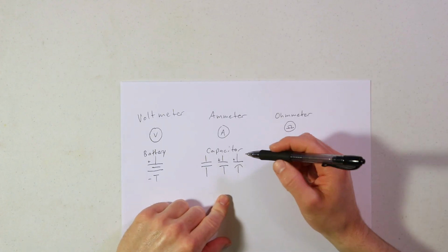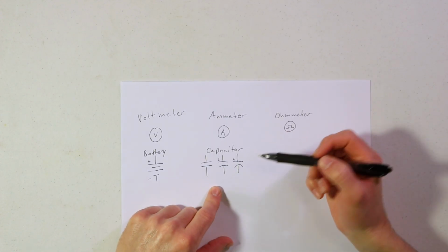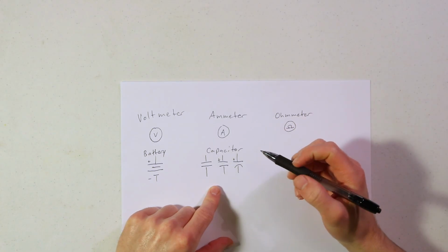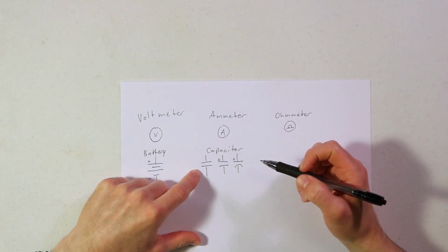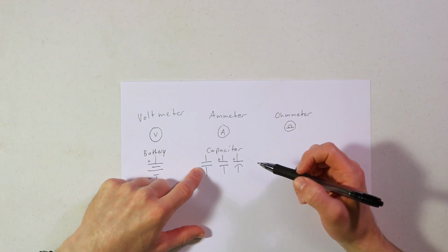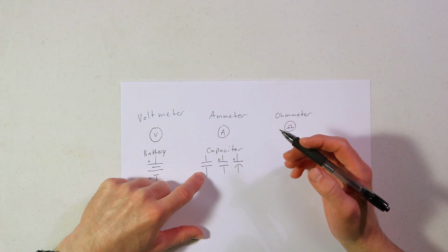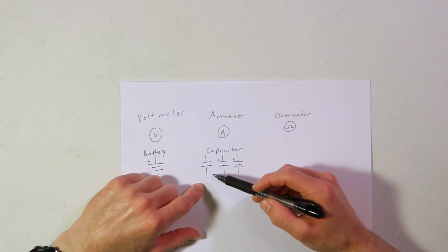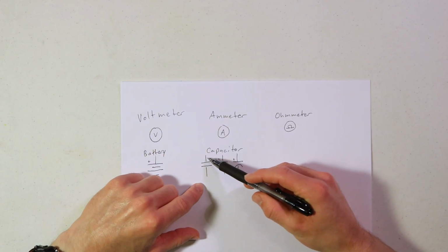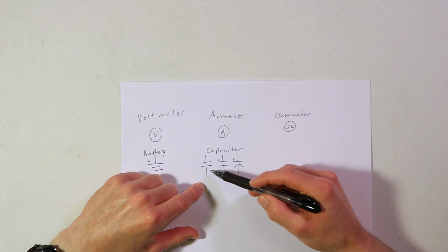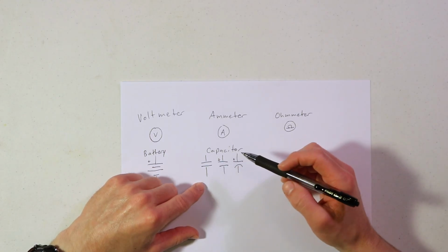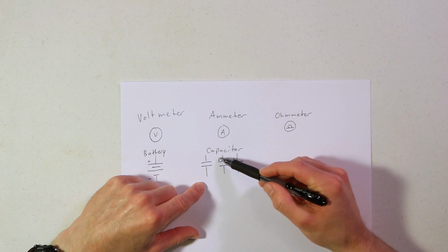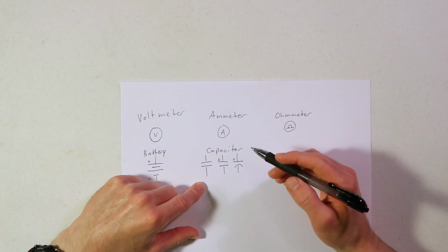The circuit symbol for your capacitor is going to look something like one of these, depending on what the capacitor is. For non-polarized capacitors, it's going to look like this one, where you have just the two lines here representing the two parts of your capacitor, the two sides, positive and negative. But for non-polarized, it's not going to matter which way you have it installed, so this is just going to represent, it could be positive on this side and negative on that side, or the other way around, positive on top, negative here. For polarized capacitors, you would normally want to do it something like this, where you can at least put a plus on one side to represent that that's the positive lead.